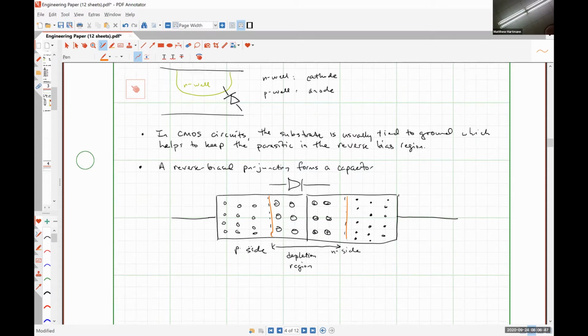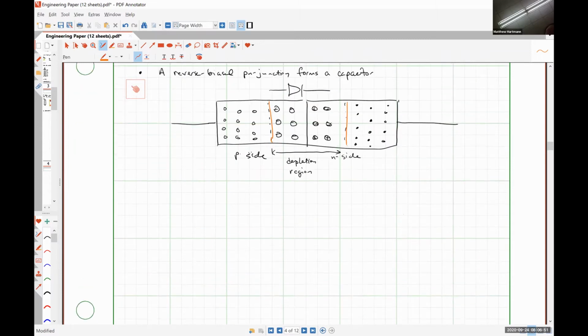All right. So in this particular capacitor, the capacitance is modeled as CJ, which stands for junction capacitance, is CJ naught, which is the unbiased junction capacitance, divided by a factor of 1 minus VD, which is the biasing voltage, divided by VBI, which is what's called the built-in voltage of the junction, raised to the mth power, where M is the grading coefficient.